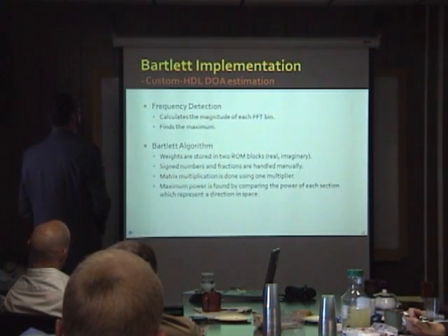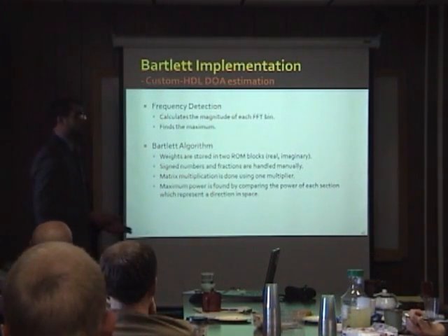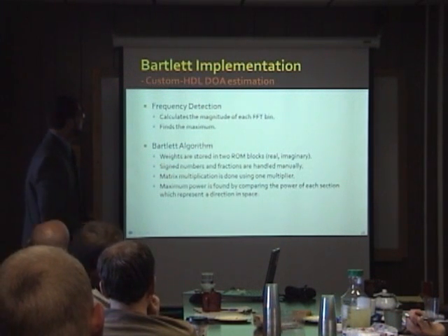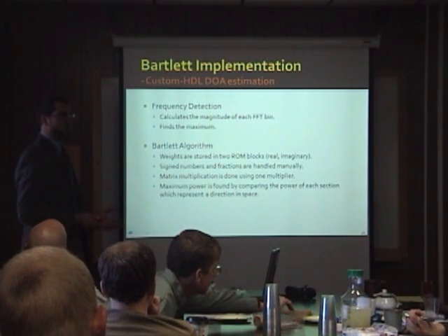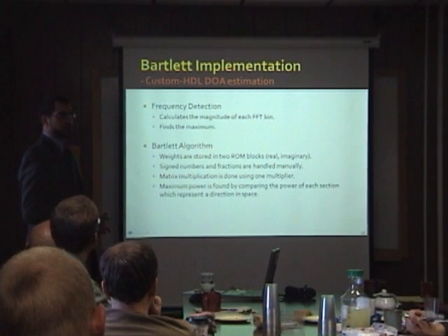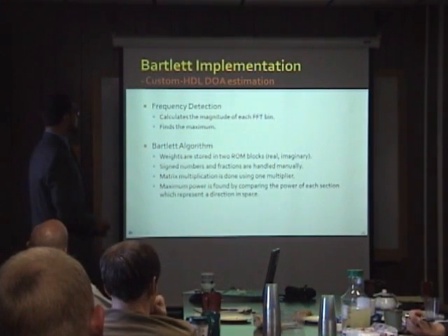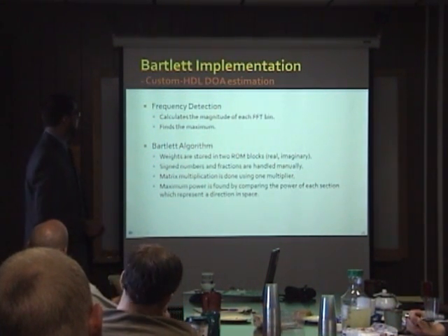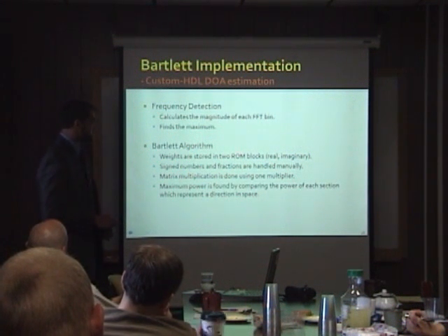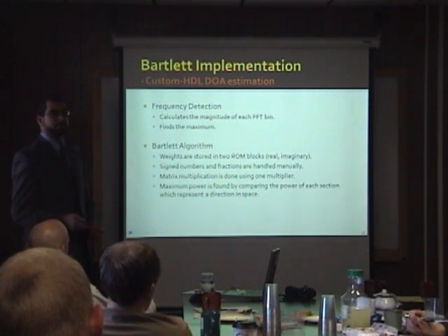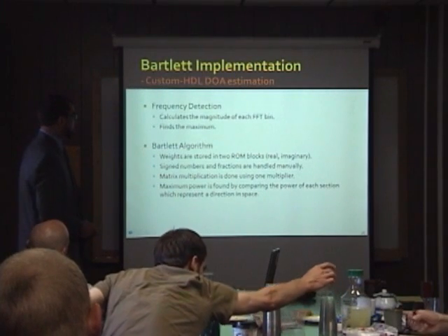And then for detecting the frequency, we calculate the magnitude of each FFT bin in memory, and then find the maximum, which represents the frequency. And in the Bartlett algorithm, we stored the weights in block ROM. This way, we don't have to calculate in real time.